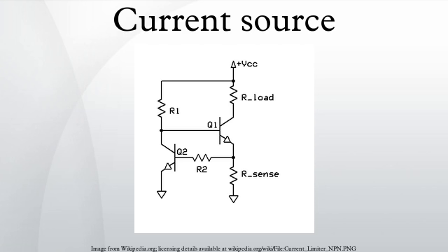Zener diode current source. In this bipolar junction transistor implementation of the general idea above, a Zener voltage stabilizer drives an emitter follower loaded by a constant emitter resistor sensing the load current. The external load of this current source is connected to the collector so that almost the same current flows through it and the emitter resistor. The transistor Q1 adjusts the output current so as to keep the voltage drop across the constant emitter resistor R2 almost equal to the relatively constant voltage drop across the Zener diode DZ1. As a result, the output current is almost constant even if the load resistance and or voltage vary.